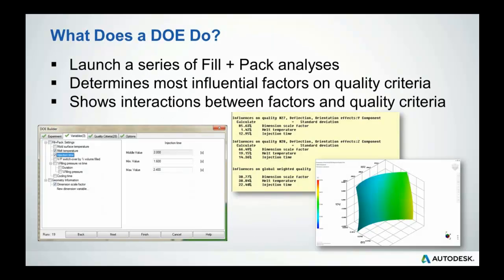So Jeff? Yes. Does doing the DOE in simulation eliminate having to do it in reality then? In many cases it does. If you think about the point of a DOE, it's typically to find what those input variables are and what their influence is on the part. So if you do this in a simulation package, you can find that same data without wasting the time on the injection molding machine.